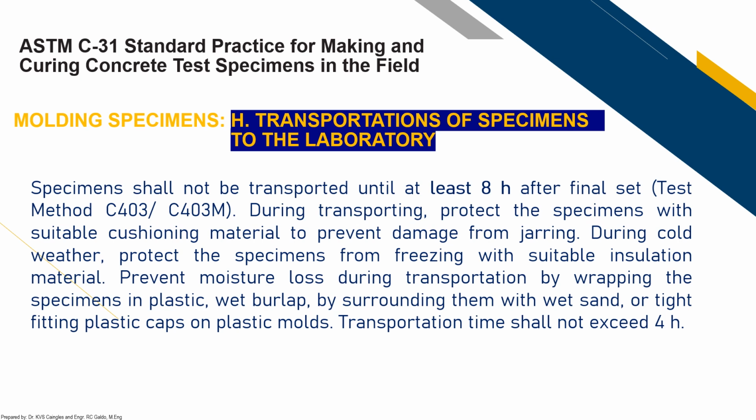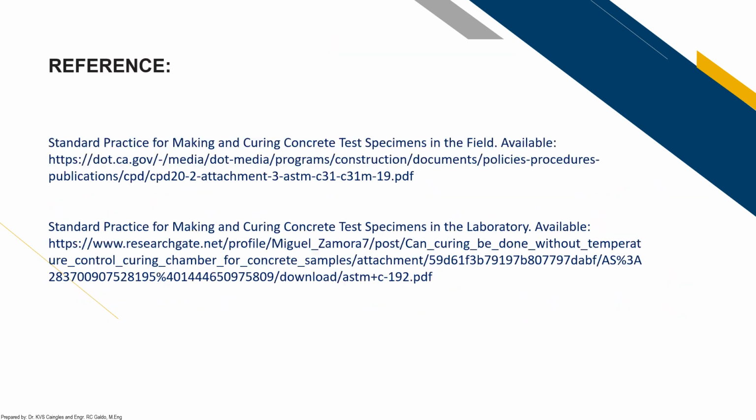Now, during transporting, protect the specimens with suitable cushion material to prevent damage from jarring. During cold weather, protect the specimen from freezing with suitable insulation material. Prevent moisture loss during transportation by wrapping the specimen in plastic, wet burlap, or by surrounding them with wet sand or tight-fitting plastic caps on plastic mold. Transportation time shall not exceed 4 hours.